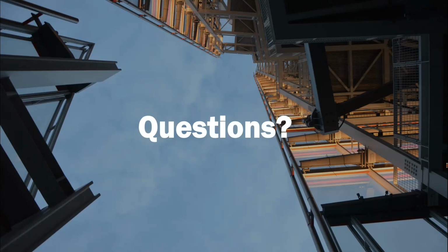And then there's another one coming from Bill here, and that is, what's he asking? I'm trying to read this. What happens if you change your mind about who's going to manufacture your ductwork? Good question. So in Revit, you can actually bring in a different service with a different database configuration. You can't bring in a separate database, unfortunately, but you can populate that iteration theoretically with a different service exported from a different database, and it should enable you to re-optimize your straights to a different length.